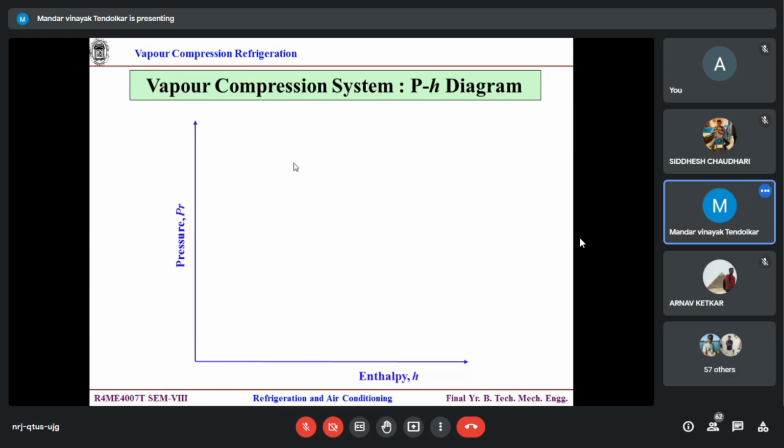What I need to know is the basic part, the condenser pressure and the evaporator pressure. That is why we suitably convert this entire graphical interpretation to the pH chart, so that I can directly draw a horizontal line for the condenser pressure and another horizontal line for the evaporator pressure. Why would pressure change? Whatever the phase, pressure remains the same, correct? Liquid pressure or vapor pressure, it is one and the same. It's only that the enthalpy would change. So on the y-axis there is pressure. On the x-axis I will take the projection so that I directly read the enthalpy value.